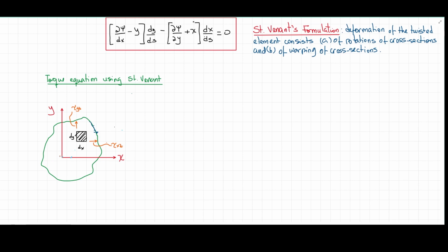Now, if I wanted to know the moment or the torque produced by these shear stresses on this differential area defined by dx times dy, I need to know definitely what's the distance from the application point that I'm going to take as being this center here, O. To calculate that moment or torque caused by those stresses, it's going to be the perpendicular distances from the origin to each one of those application points, symbolically representing those stresses. Of course, something like this.